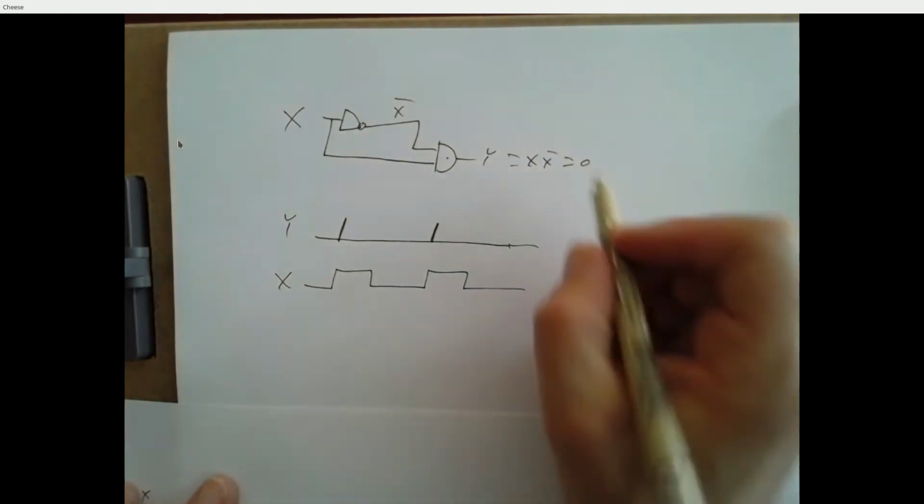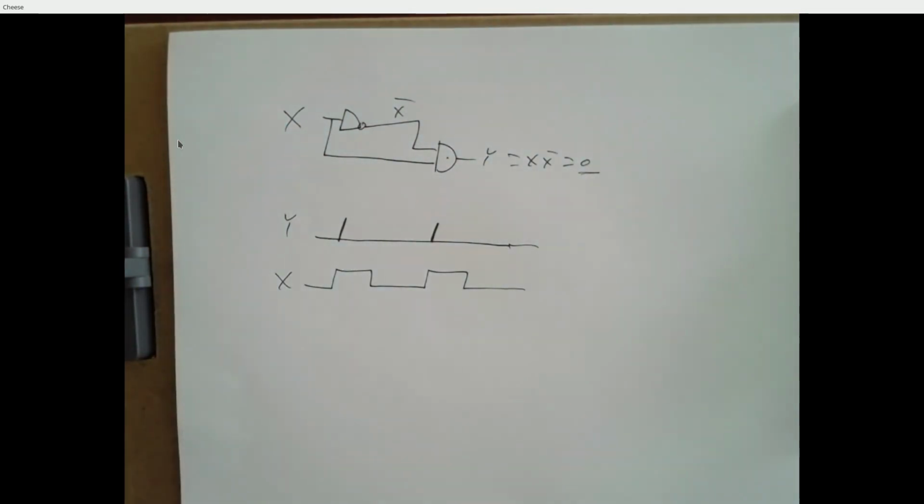So your output's going to be different from what your truth table says it should be. So for the logic gates, if we have a higher range as far as the propagation delays go, is that a better chip because it has a higher or wider range? In some sense, your best chip would be one with 0 propagation delay, because then this would never be an issue.